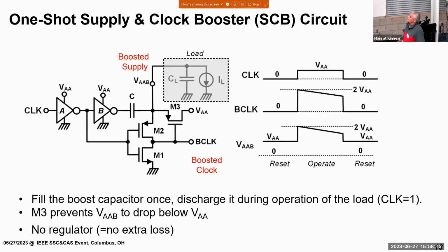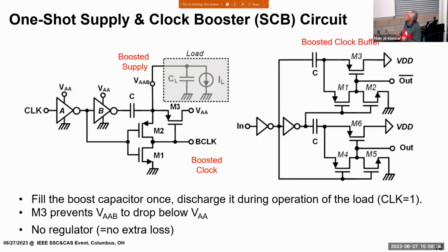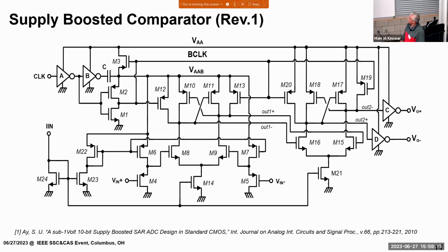Okay? And here you don't really need to have a regulator, no LDO, nothing. As long as you get your signal operated or passed through your electronics here before it drops down to the VA level, you are going to be okay. Now, obviously, for analog signals, you're going to see this drop on your analog signal passing through. But again, if the operation is short before it drops too much, it's going to be okay. And obviously, you can have an inverse version to drive the CMOS switches with the same idea, same holding capacitor, and be able to generate a logic inverse version of that clock signal.